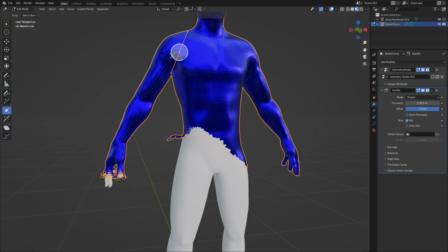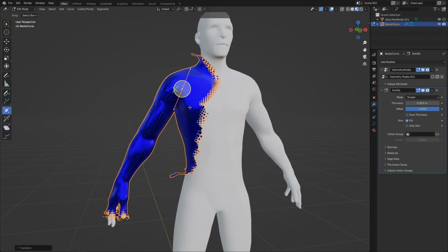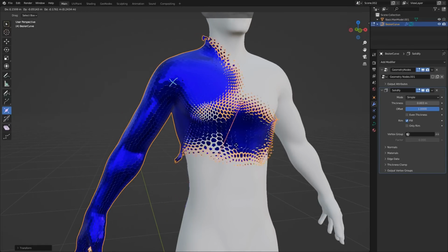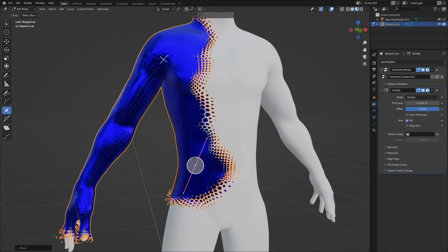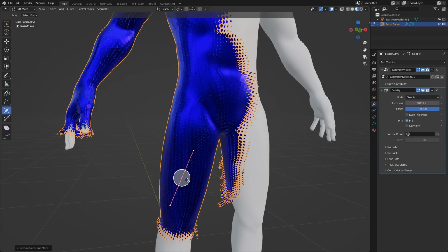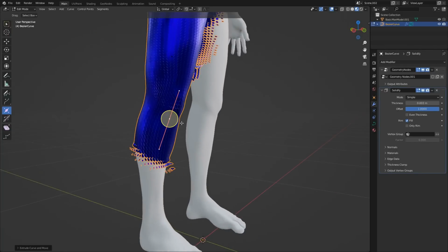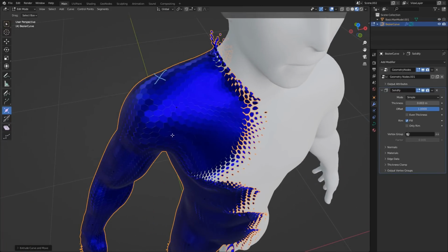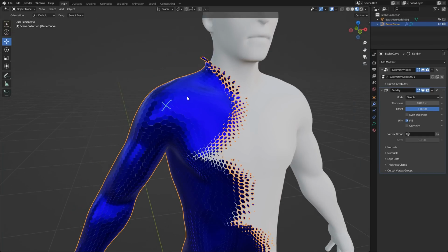So instead of scaling the radius infinitely, I'm just going to press E to extrude this into another, to continue the spline. And now this has again control over this area, and you can keep pressing E, changing the radius, and you can get some pretty cool effects going like this. Okay, so that's great for hexagons. If you want just a bunch of hexagons on your surface, it's fine, gets the job done.